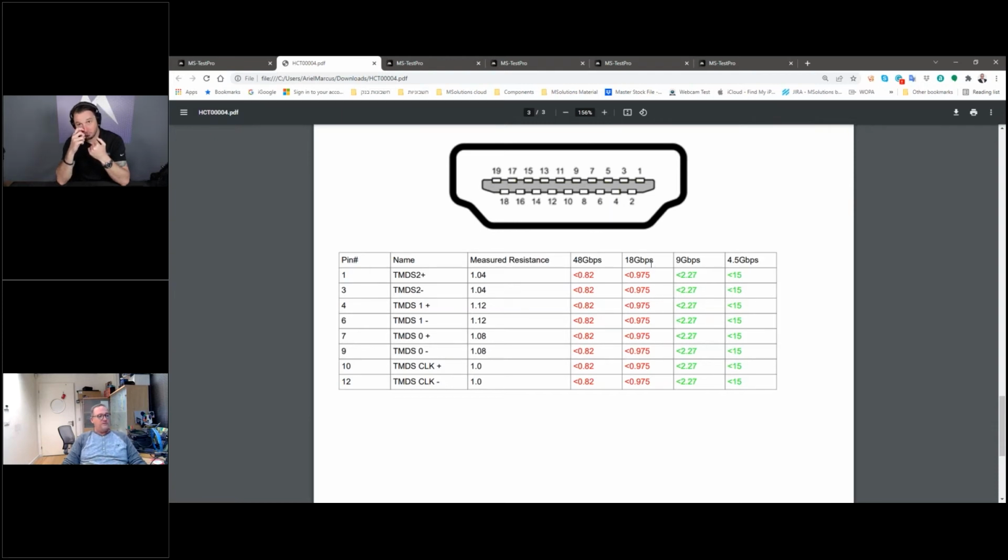Now, those two are actually different with every transmitter and every receiver of HDMI. There are no two that will be the same. Sure. So if you are, from one side, improving the driving of the signal out, and on receiving you are implementing unique algorithms to recover the signal, you're actually hiding the artifacts that are being created inside the cable.